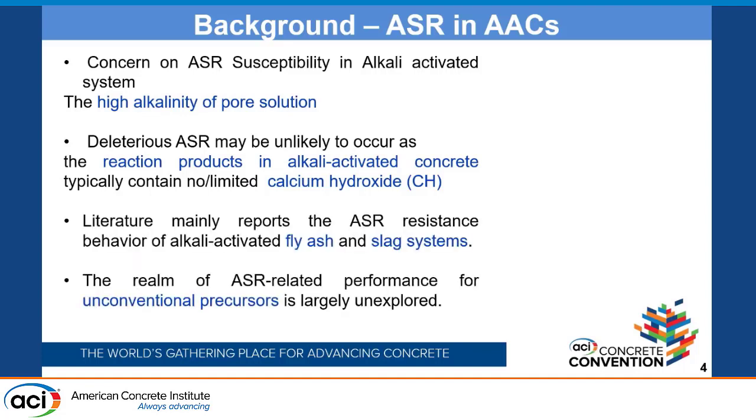But the literature reported for alkali-activated fly ash and slag says that this reaction is unlikely to occur for various reasons, one such being the reaction product chemistry, having a limited amount of calcium hydroxide, which is one of the prerequisites for the ASR reaction.